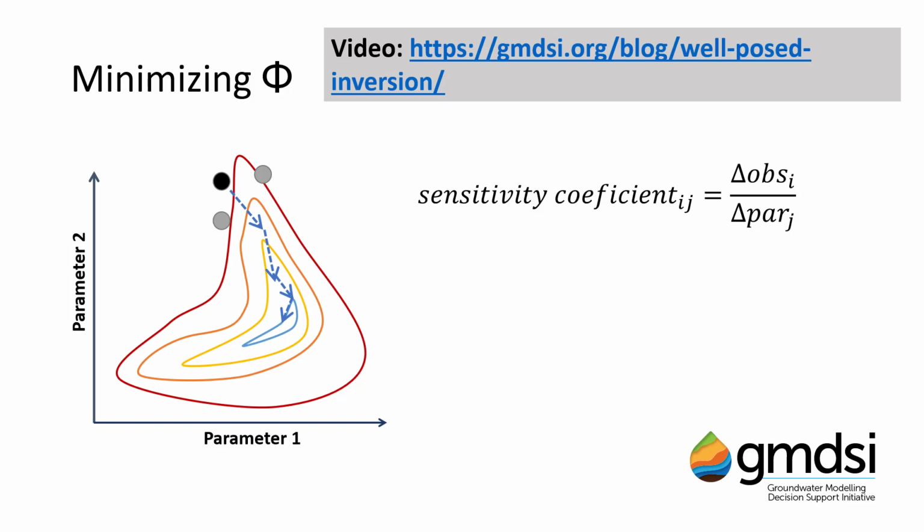Thus, instead of attempting to estimate the values for all model cells, we can reduce them to a manageable number of pilot points, while still retaining the ability to express heterogeneity. Of course, the ease of access nowadays to parallelized computing, whether through local networks or in a cloud, allows many model runs to be carried out in parallel, speeding up this process significantly.